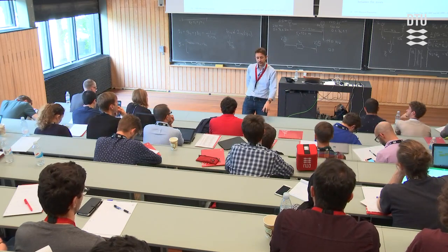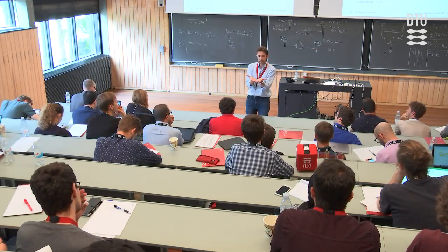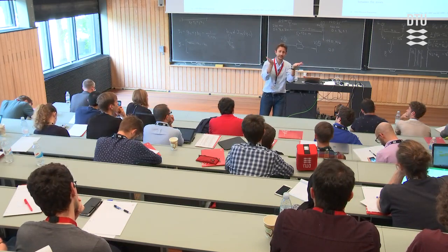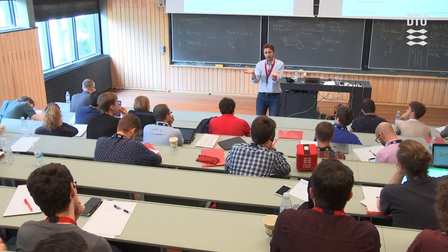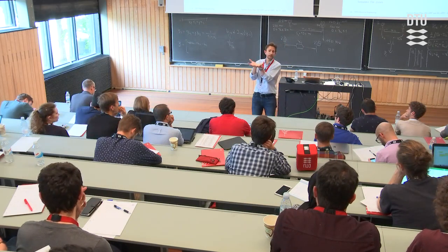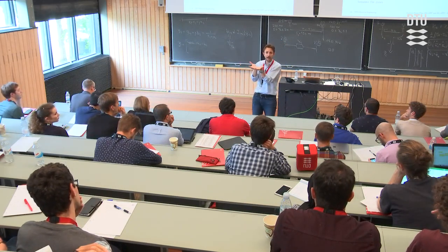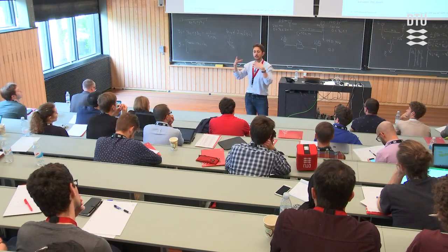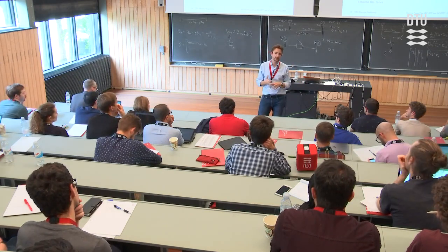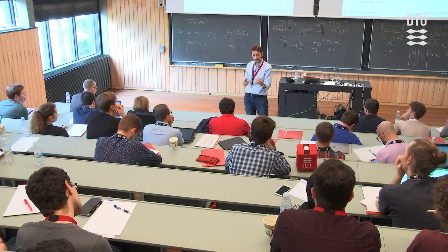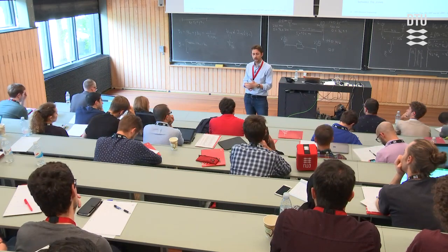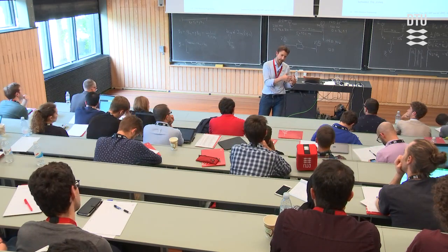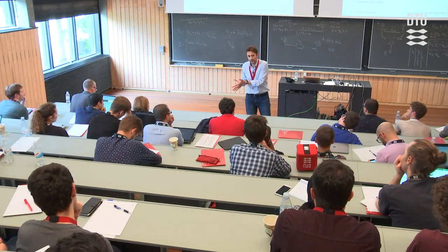There are some formulations because sometimes your objective function is very flat. This means that there are many solutions that have exactly the same cost, so the optimization does not know what to pick, or picks one of them randomly. And then you might want to drive your optimization to one of those solutions that also has a minimum angle difference, because in that case, you also minimize the flows, and then you minimize the losses on the line. But this is a multi-objective optimization, since you have 2 different objectives, and you must be very careful how you define the weights. Because if you put a large weight on the voltage angles, then you don't get to the minimum cost solution, right?